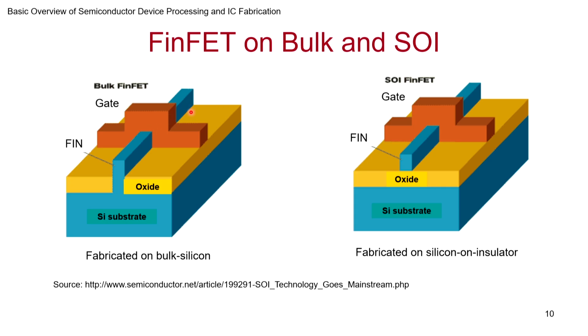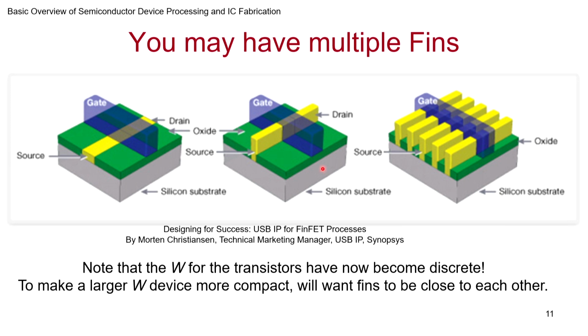So typically you want to keep it symmetric, and also of course easier for fabrication. Now at some region you have a thin gate oxide, you deposit the poly and you build it. So if you look at it, it is not just a single fin that can be built. As I said, this is the traditional, as we have already seen, a traditional device which is flat. All that you did was this channel region underneath is actually going up, and of course when it is going up, you need to make the source and the drain also follow that, so that you can get electrical contact and continuity, and then of course the gate around it.